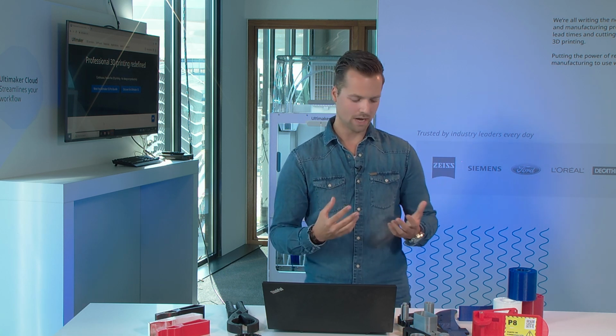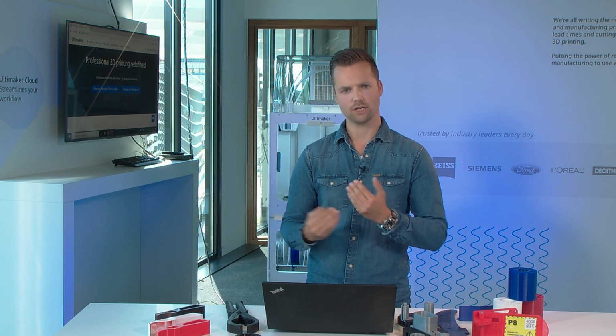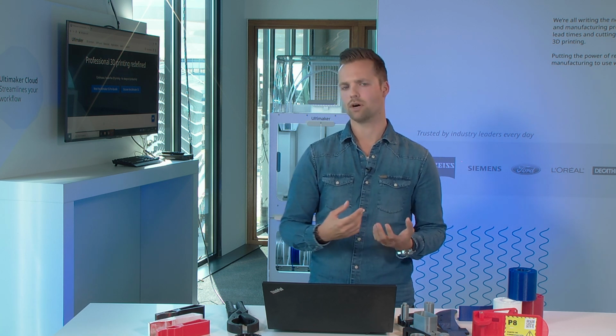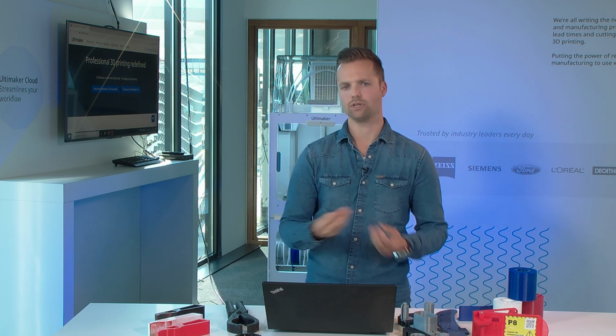With dual extrusion, I mean, for example, when you have a certain labeler and you want to incorporate text for the operators to understand what kind of tool this is, indicate maybe the height, specify this. You can do that in a 3D model. So you have your actual model, and with a different color, for example, you write in the name, and in Ultimaker Cura you can specify which extruder is being used for which part. And there you can really label your parts.